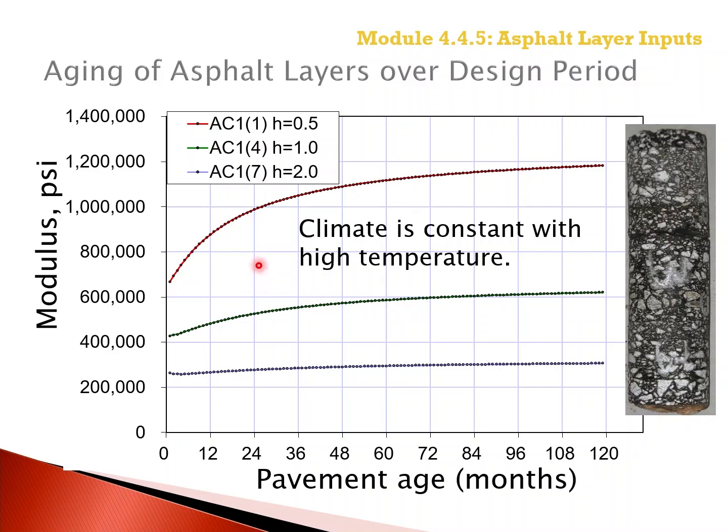Long-term aging has been defined as 10 years of service life, but the long-term aging process used in the laboratory does not distinguish between wearing surfaces and underlying asphalt base layers. The long-term aging procedures were developed for the wearing surface, at or near the surface.